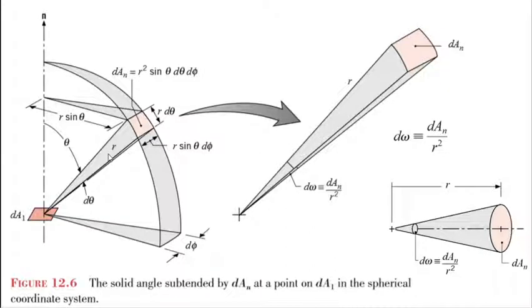So if I am looking at radiation emitted in a particular direction, you say that it is emitted over a solid angle d omega in the direction omega, and that omega would be a function of theta and phi, right? So that is the thing. So if you are looking at radiation emitted over the entire hemisphere, then that will be radiation emitted over 2 pi steradians, that is, omega equal to 2 pi over the half of the surface.